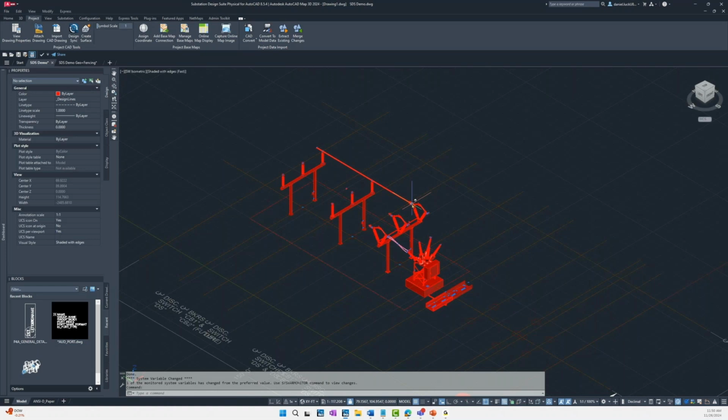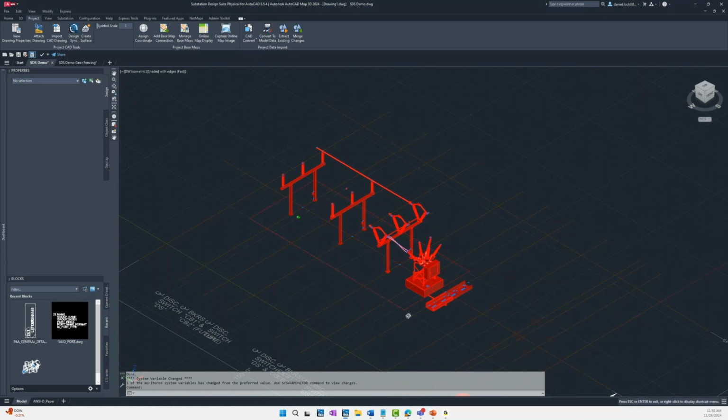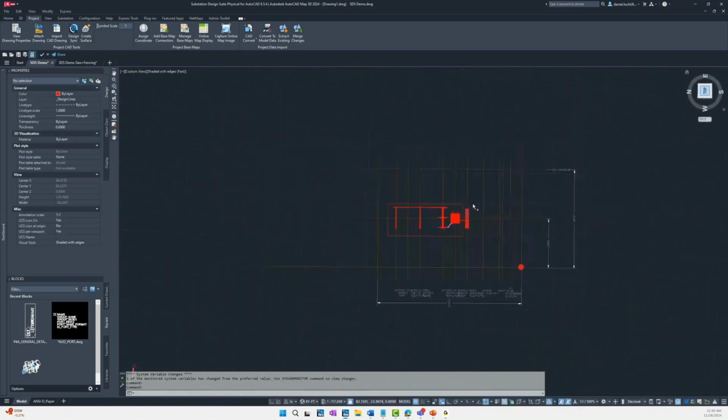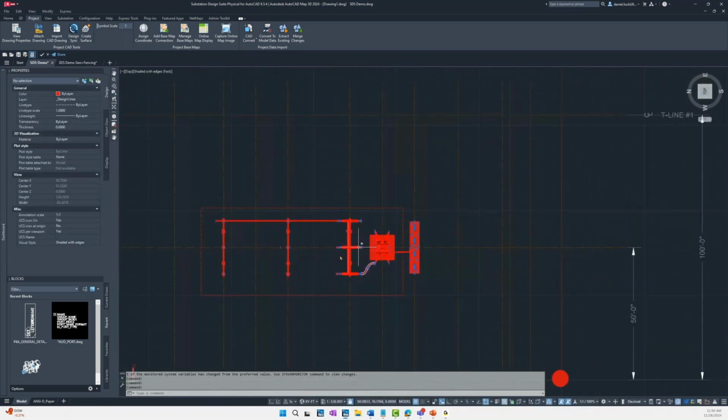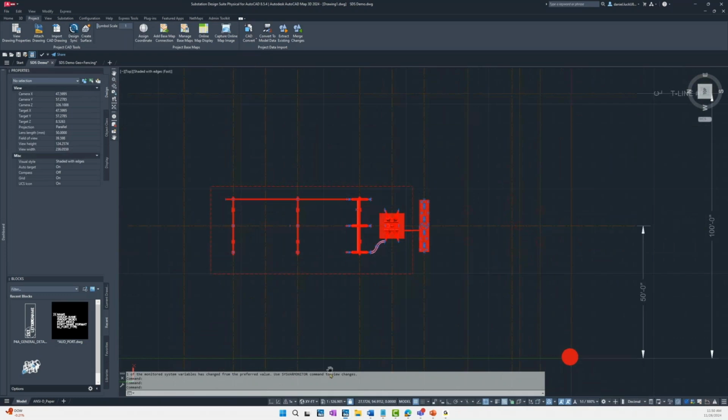So this AUDEXTRACT command in P4A allows multiple designers to work on small different sections of a substation at a time while extracting and updating each of their changes back to this main 3D station file. Very useful when you talk about multiple projects being done at a site at one time. And this can be done easily in P4A with just a few commands.